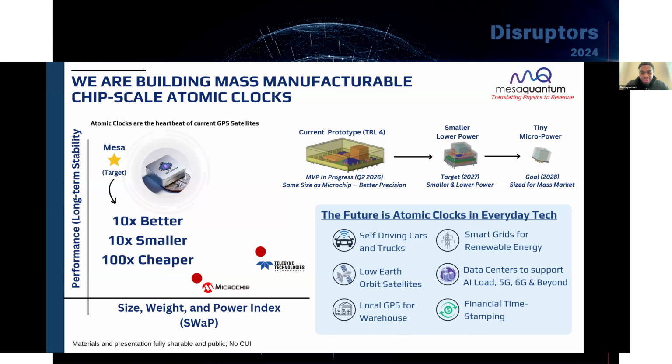The chip-scale atomic clocks are essentially miniaturized demonstrations of what we currently have in our GPS satellites. They've worked decently well for the last decade or so, mostly aiding in military GPS denied environments where you need some type of holdover on your timing signal.